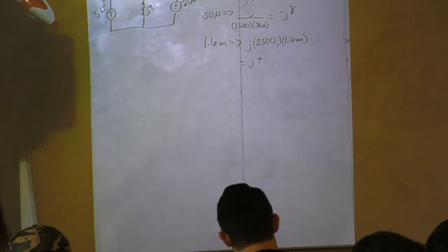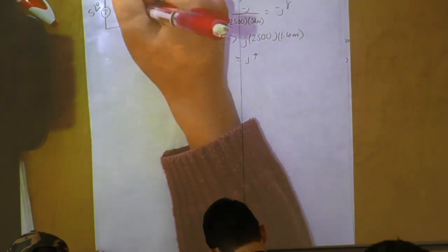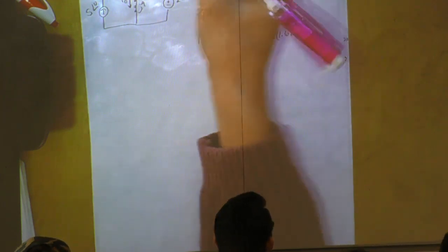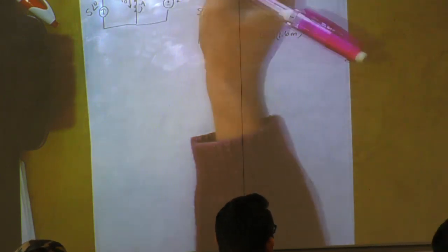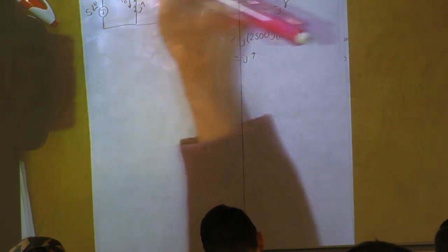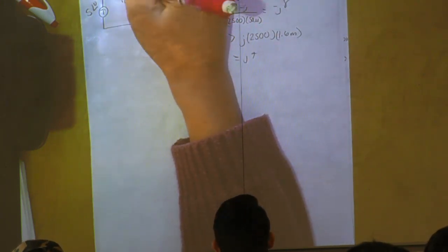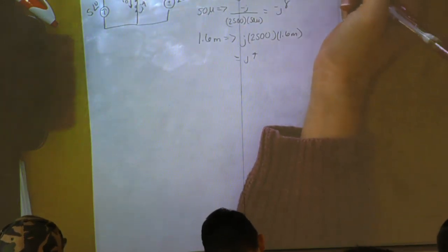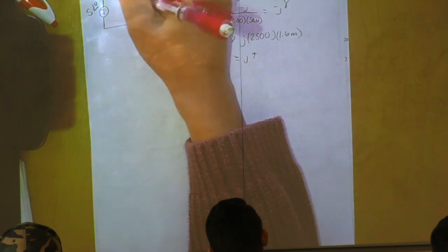So we want to find the output, which is over the inductor. We can do KCL. We'll have this node. We know this node, right? And then we'll have this node. So we'll do V1, V2. V1 will have 1, 2, 3 currents.